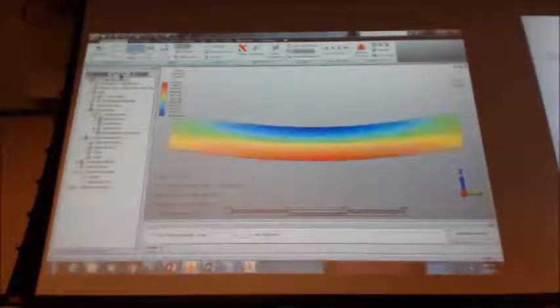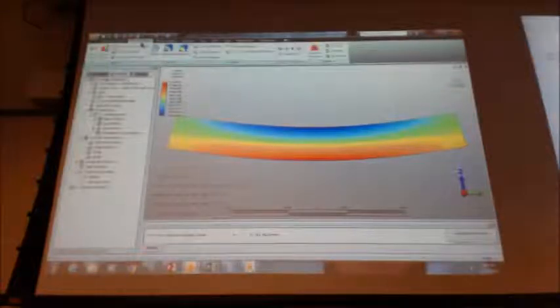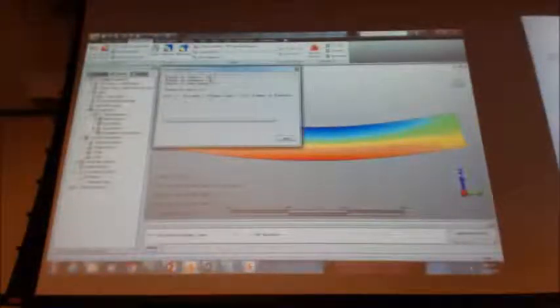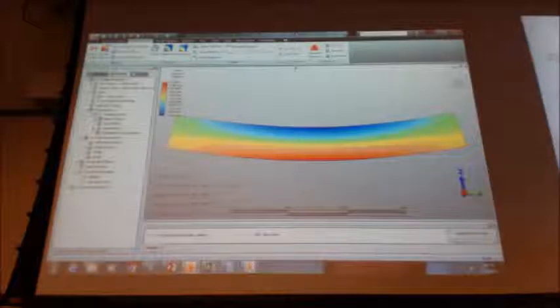If I go back to scenario 1 and look at my results, if I go to inquiry and model statistics, then it'll tell me my number of elements and nodes. And then I was putting that number on my design scenario so I could keep track of where, and whether it was a triangle or a quad. That was just my way of keeping track of what was what.